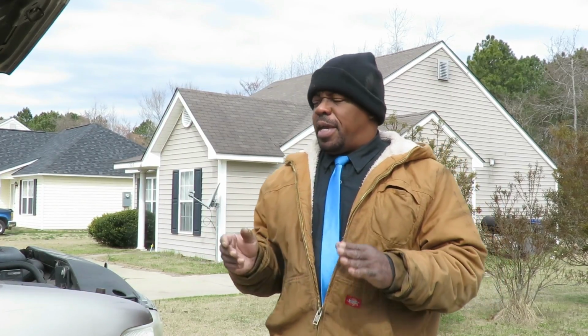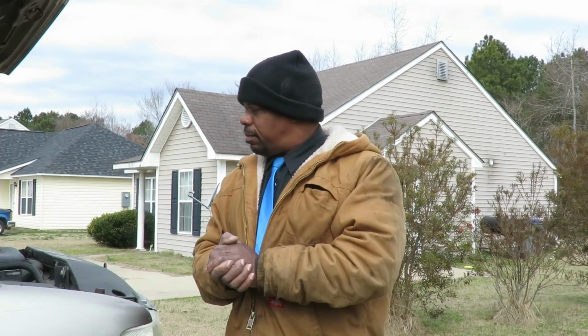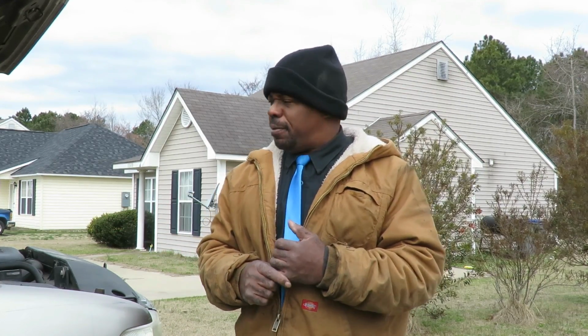We'll be right back. All right, guys, before we proceed, in order for your ABS system to work properly, the computer has to know the speed of each individual wheel. Now, sometimes on rear-wheel drive vehicles, there's only one sensor, and that's for both wheels. In this problem, the computer does not know the speed of the left front wheel, and if it doesn't know that, your ABS system will not work properly.